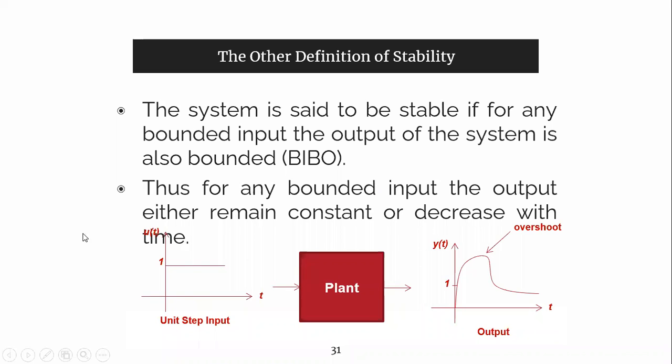See here the constant term before applying the condition. Here is the time domain, which is again the unit step function, so zeros and one. By taking this, you can identify this is a unit step input, and after applying the input, after excitation, you will get such a type of graph curve. Here you can identify the overshoot, this is the output and this was the input. So at that time we can identify easily.